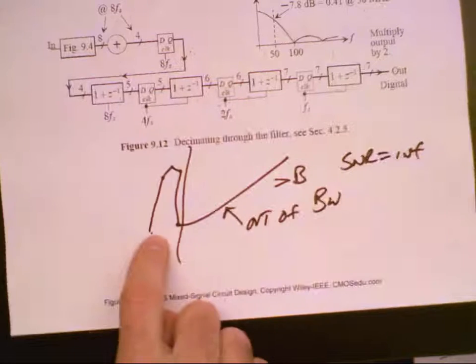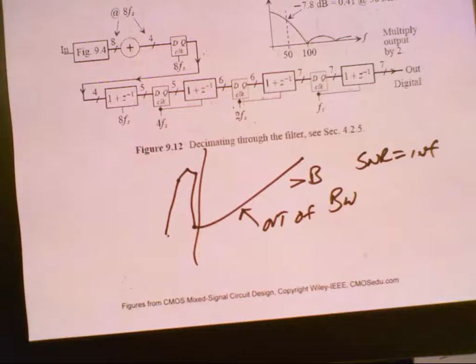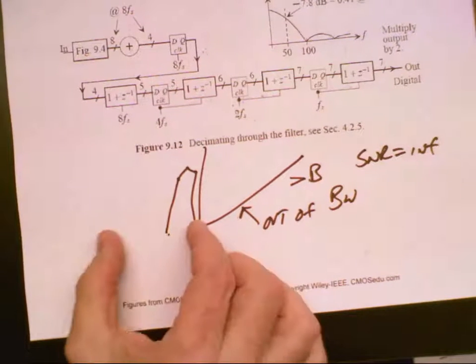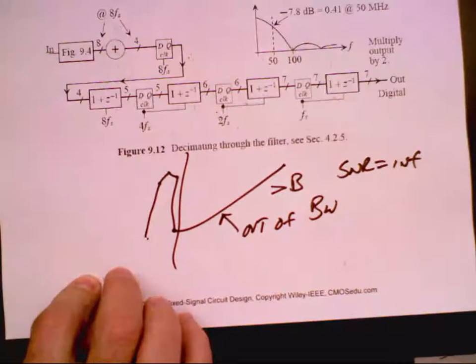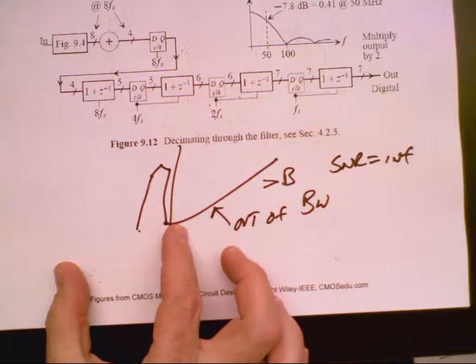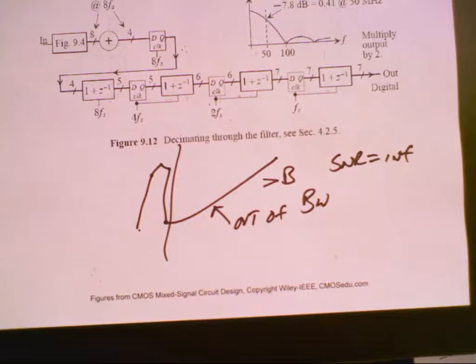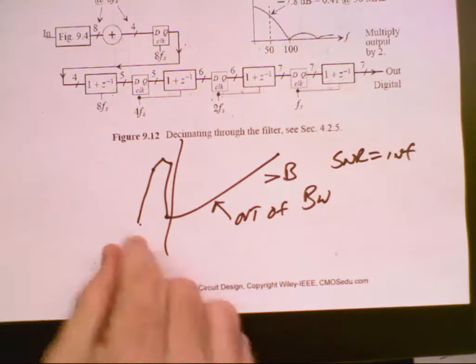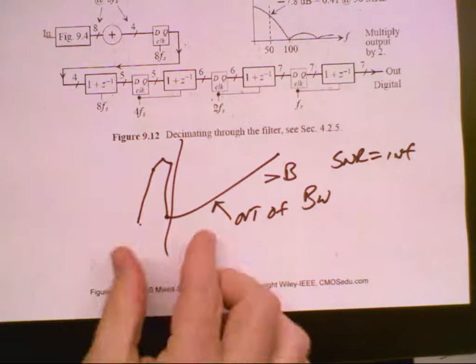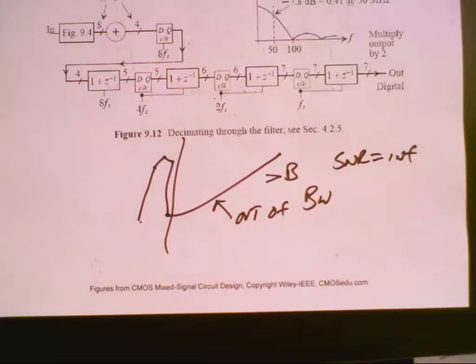You've got to have points of noise in here. If you don't have points of noise, you're going to have a really high signal to noise ratio. Well, no, if you go to longer times, you have to simulate longer. That's the problem, because if you don't simulate longer, you don't get the points in the lower spectrum. If you don't have the points in the lower spectrum, when it adds up the power in those, there isn't any, and that's the noise. Then your signal is this, and the noise is basically two points or whatever it is, or none, and so you have a super high signal to noise ratio. Okay? All right.